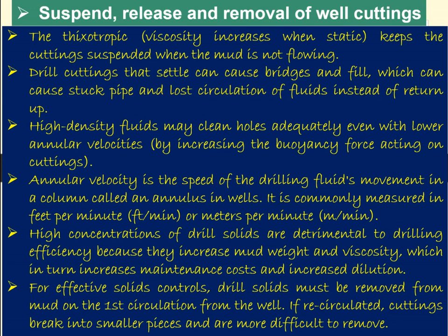Suspend, release, and you see the thixotropic property means viscosity. High viscosity automatically increases in static condition. Suppose you are drilling a borehole, and when taking up the core, for a short time that condition is at rest. At that time, the drilling fluid, by its thixotropic property, has its viscosity automatically increase when static, and it keeps the cuttings suspended.